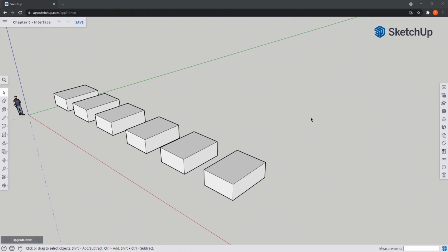Another important feature that we can do with the mouse is the selection area. And here, if you know how to use AutoCAD, it works similarly. First, I need to click in an empty space with the left button and hold it. When you move the pointer, you realize it opens a rectangle. That's a selection area. But now there are two ways.